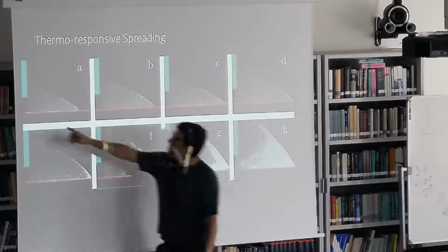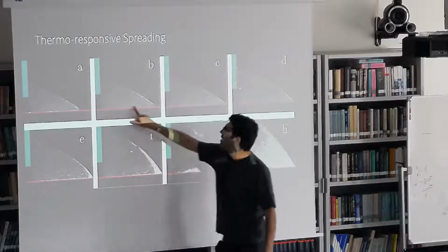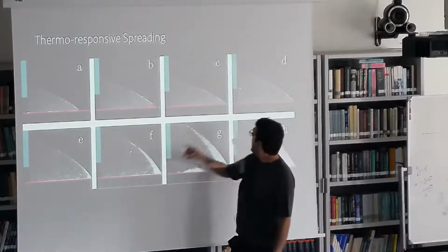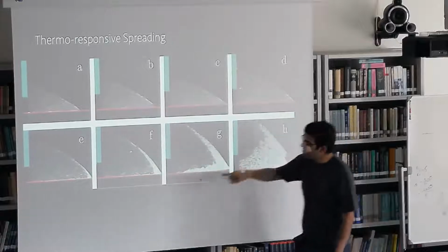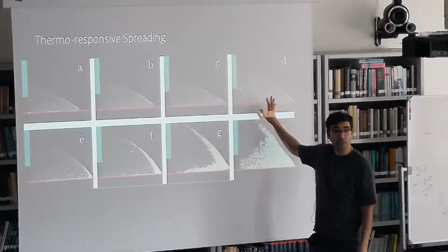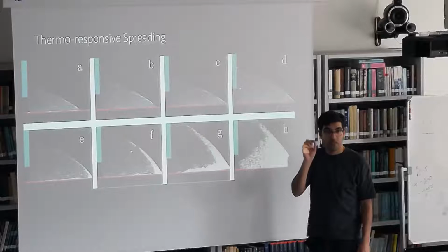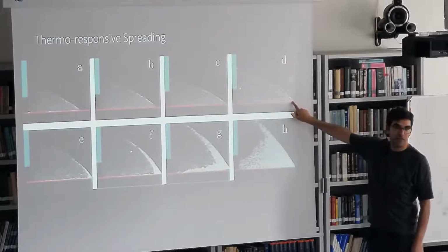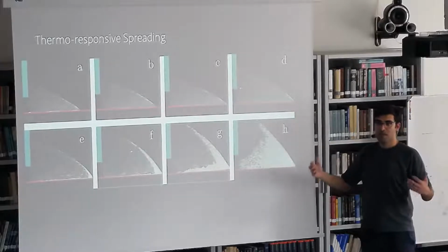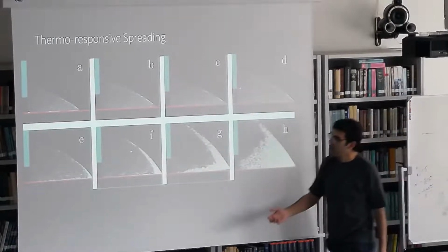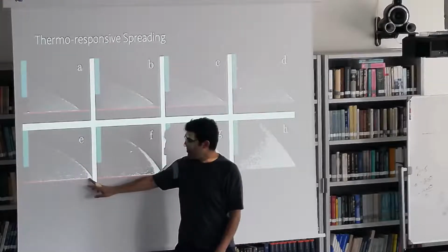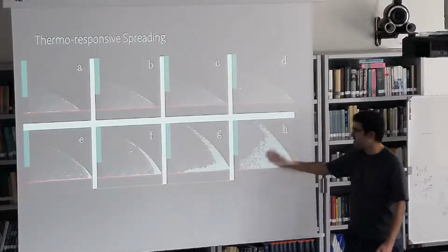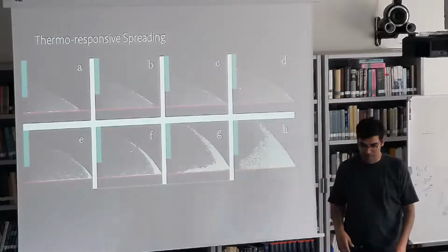We inject the liquid from this nozzle. It starts spreading nicely, as capillary spreading looks like. At some point it stops spreading, and we don't see any signature of solidification. That gives us the hint that what stops the droplet is a very, very small solidification at the contact line, in fact. And that's enough in a low speed spreading for the droplet to stop. What happens later is like a previous experiment I showed you. You get this skin first, and then the bulk conduction kicks in, and the droplet fully solidifies, in fact.